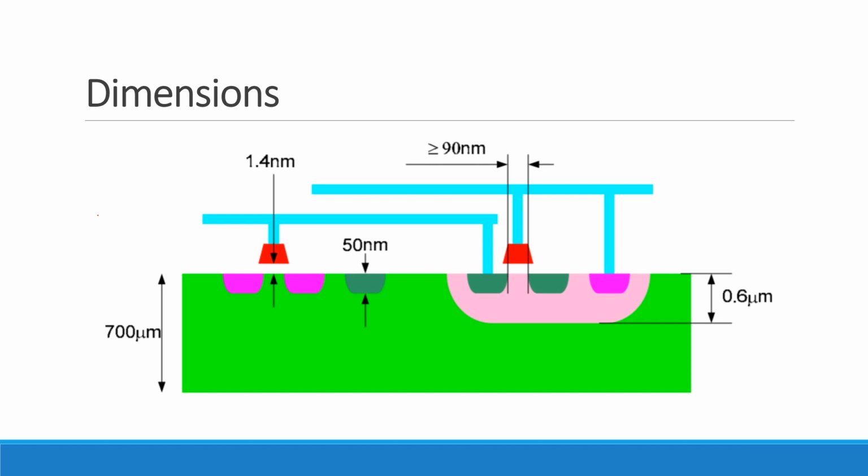But that's turning out to be a more interesting relationship these days, because now people are even talking about transistors where rather than the effective length being shorter, it's actually longer. So if you look at a 22 nanometer process, people are talking about effective channel lengths of 23 or 24. Okay, if you're interested in why, come bug me, I'll explain it, but just keep in mind, process technology does not necessarily mean the effective channel length of the device. Okay?